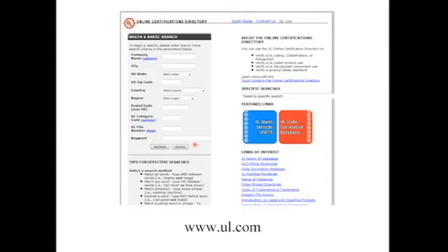If you're looking for, let's say, fire-rated luminaires, you have to know some of the terminology. Light fixtures is not going to be in here. They're actually called luminaires as the technical term. If you're looking for putty pads, the fire resistive clay pads and such, the intumescent material that goes against the back of electrical boxes, they're actually under wall opening protectives. So if you just look up putty pad, you may or may not find it.